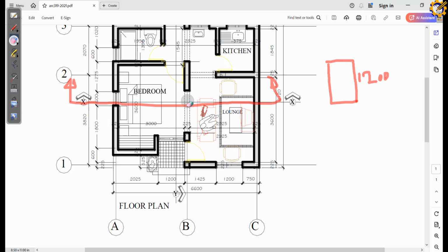and likewise on this second foundation wall we have a beam, and in most cases our beam is usually above our lintel level, maybe a block above or 2 blocks above. But for the sake of this video, I'm going to use a block above our lintel level, so take note of that. While on this third wall, we don't have any structural components, it is just a wall throughout from the foundation to the top. I have a window here, I have a beam here, so I'm going to fix that now.